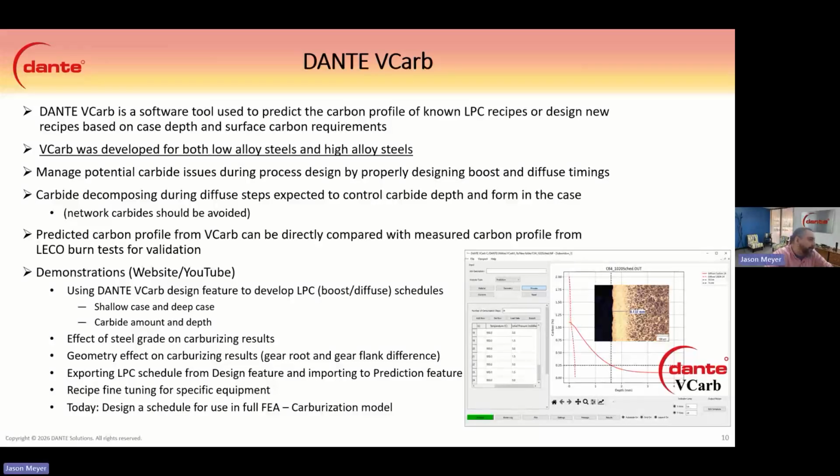A lot of the predictions that we developed here aren't just math, so they are validated with real life experiments, and we like to use LECO burn tests to validate the carbon profile based on depth, where they machine off a little bit and then they burn that, and the carbon that comes off of it is used to know how much carbon was at that depth.